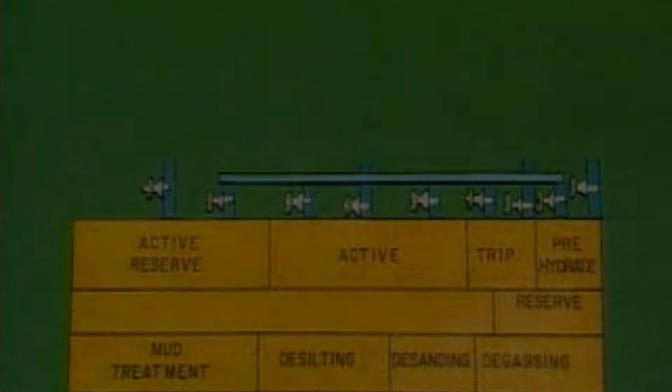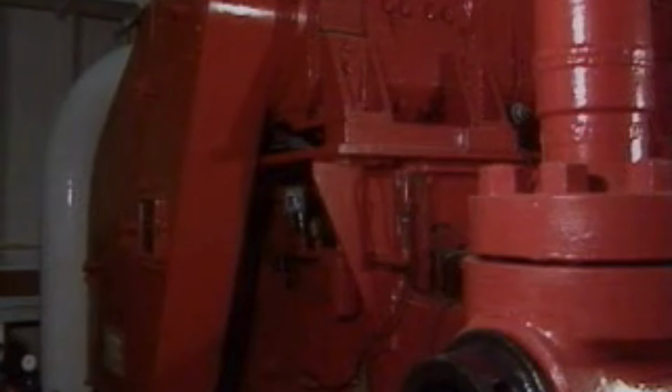Trace the pipes further, and you'll find that there are 2 routes of interconnecting pipework that tie the manifold to each of the 2 high-pressure mud pumps. One route passes through a low-pressure centrifugal pump called a charging pump before connecting to the input side of the mud pump. This pump is used to charge the high-pressure mud pumps to get them started.